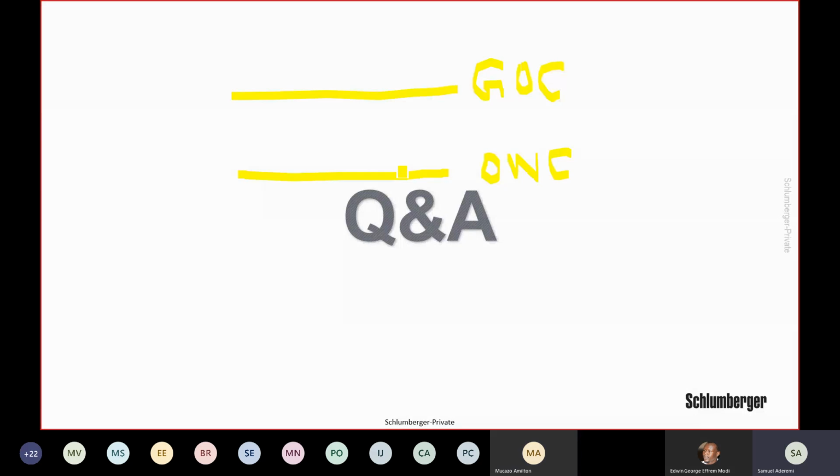So there are two ways to look at the problem, right? If you don't have the initial water saturation array, the simulator will use the equilibration method that my colleague explained previously. So let's say there is no transition zone. What the simulator will do to know the saturation in each cell is to look at the oil and water relative permeability curves that you have provided, and look at the saturation coordinate on this relative permeability curve.